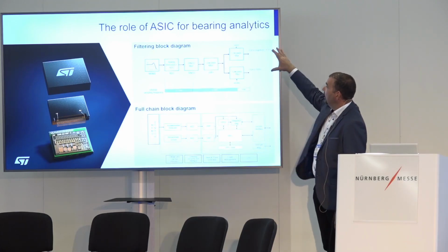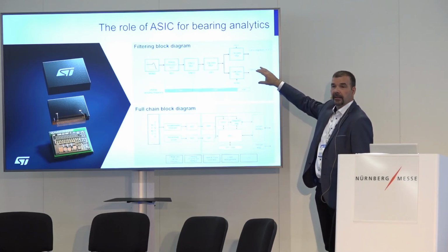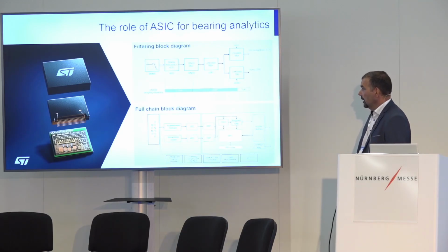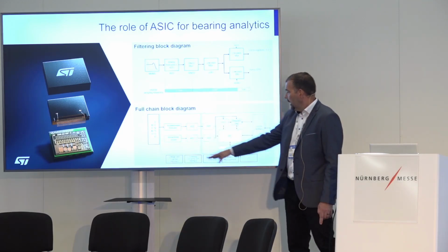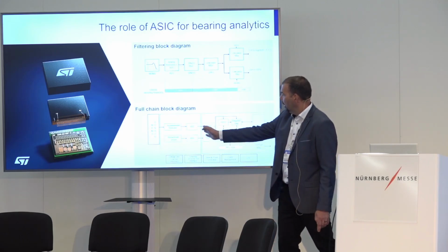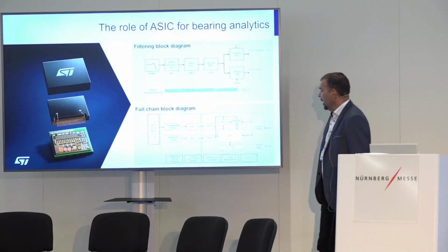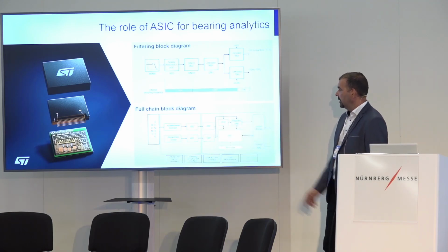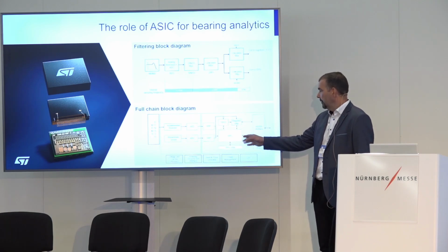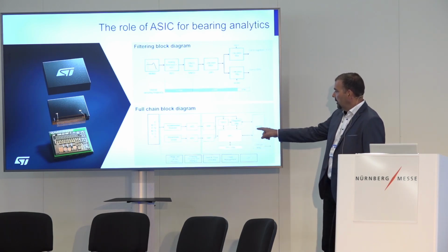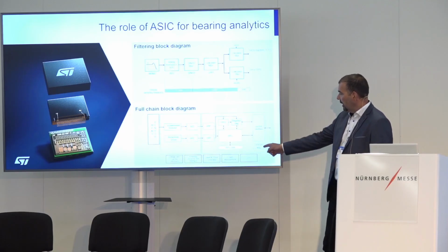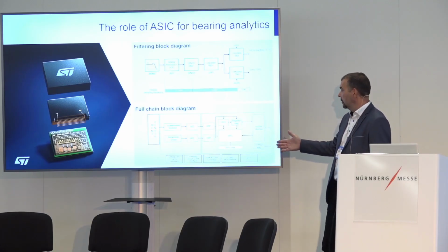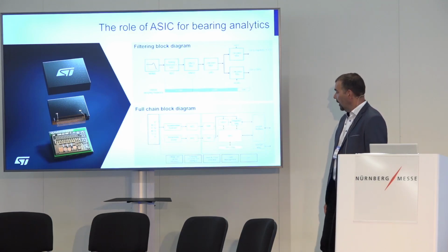So you have the data available outside, but also for the internal processing at the same time. The full chain block is visible here. Okay, so I was talking up to here, right now in this chart. And what is here in the yellow area of the ASIC, it's the embedded RISC processor. On the right side, there is the I3C and SPI interface, and of course, some interrupts. So in case you want to, for example, generate an interrupt if you are above a certain threshold of acceleration, you can use dedicated pins for it.